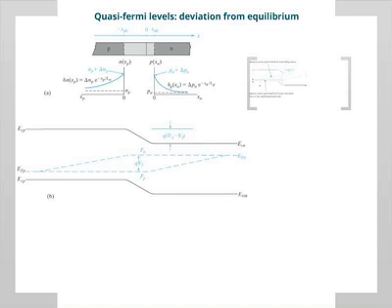Now, the intuition, before we look at the math, is essentially that recall that the Fermi level relative to the valence or conduction bands gives you an estimate of how many majority carriers are there, right? Or minority carriers, they're both related, right? So if you have a spatial variation of carrier concentrations, one would expect a spatial variation in the Fermi level, okay? But now this Fermi level is under non-equilibrium conditions, and it is referred to as a quasi-Fermi level. Okay? And you will see more about this actually next week on Thursday's lecture on optical excitation. Then it'll become a little more clear.